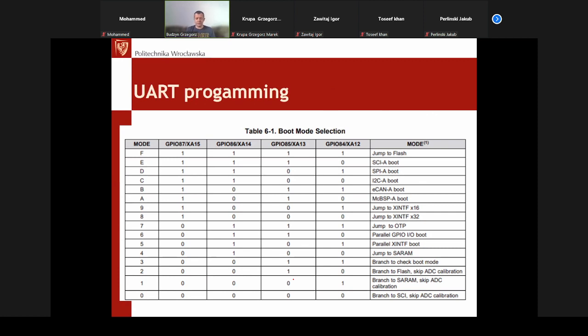I found a microcontroller from the Texas Instruments portfolio with 16 boot modes. There are modes using UART, SPI, and I2C for programming, or McBSP, or an external interface for parallel programming, even 32-bit parallel boot as well. So a couple of versions of boot.